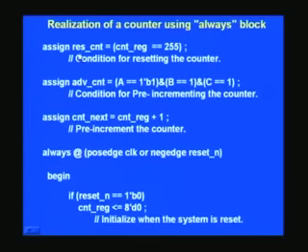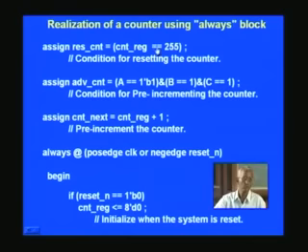So we have seen that reset counter is when counter register is equal to 255. Once again we notice that two equal signs are used here, being a logical statement, and what it does is the comparison, and if the comparison is true, then 1 is output, and that 1 only is assigned to this reset count. Is that clear? It is not the 255 that is coming over to this. This is only a single bit. The result is a single bit once again, which is assigned here, and it's all based on the counter value as such, and that's what we have written here as the comment.